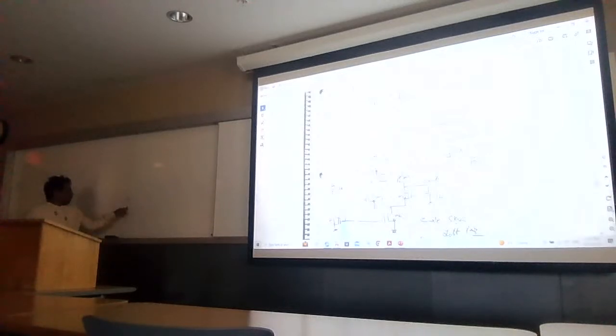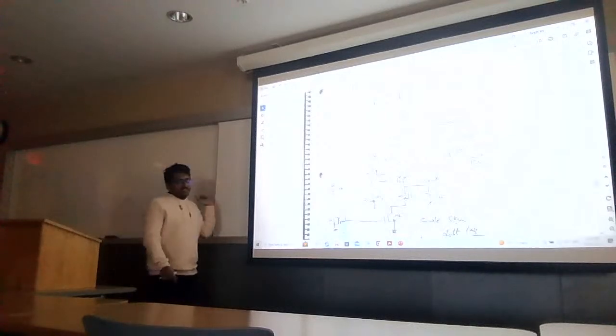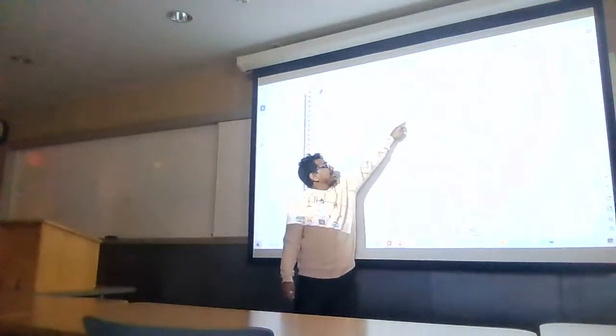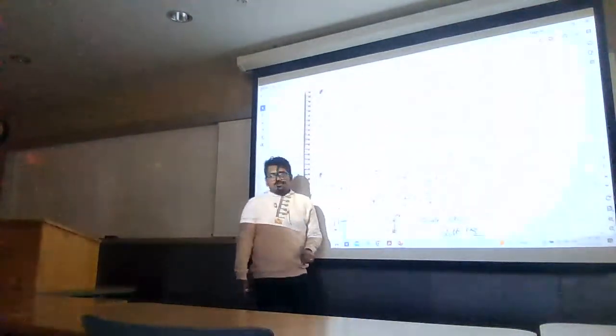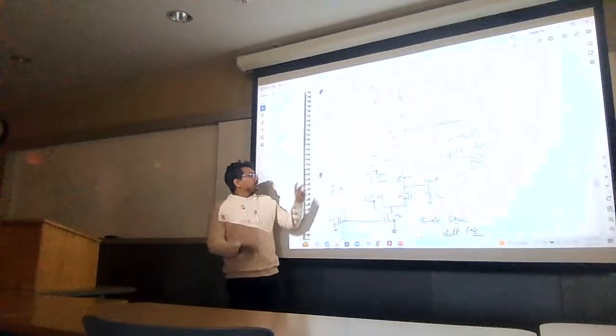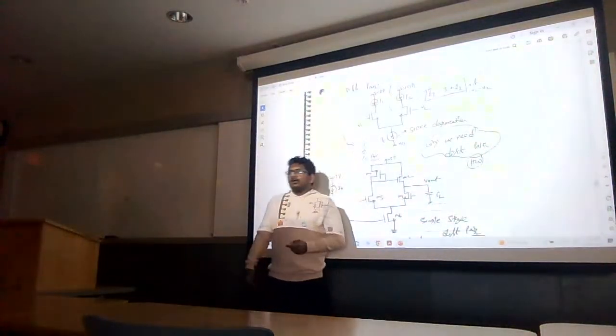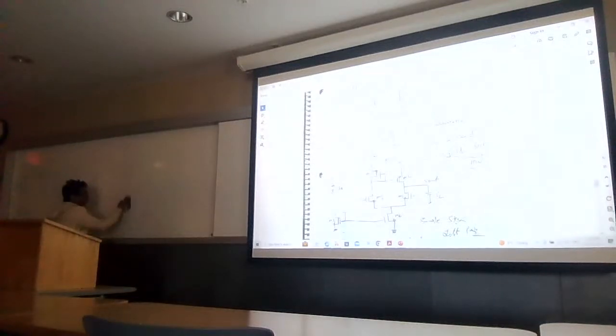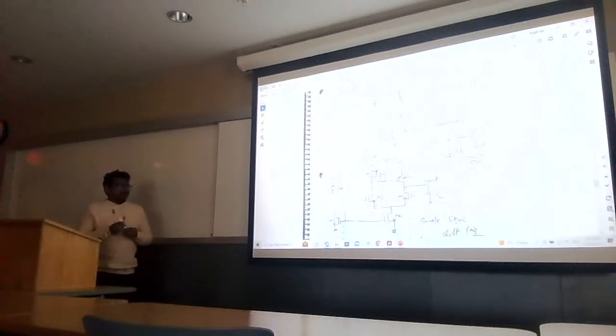And this DC voltage, let's say it is 800 millivolt, so this 800 millivolt should be applied here and here, the same voltage. As this voltage is the same in both cases, it is known as common mode voltage. It's common in both. So I am replacing this VDC with the common mode. And here, we have to apply a differential signal.